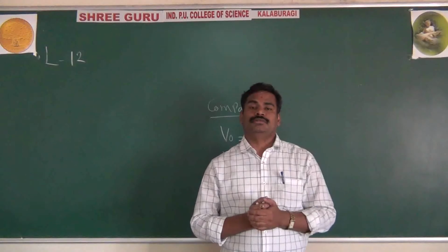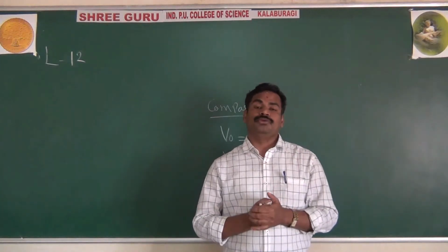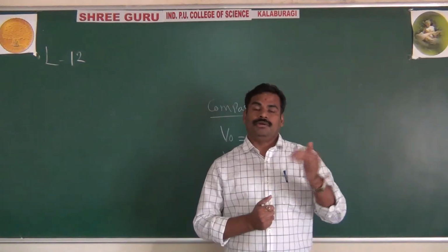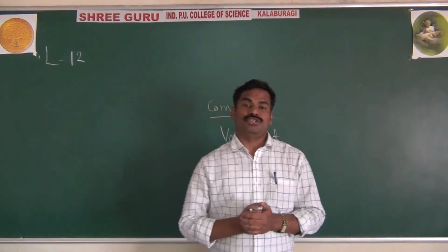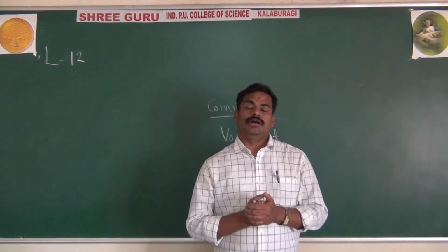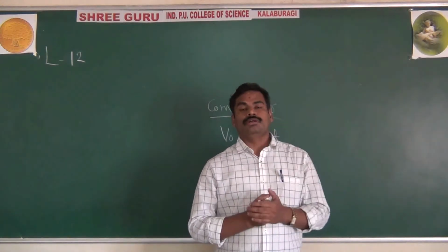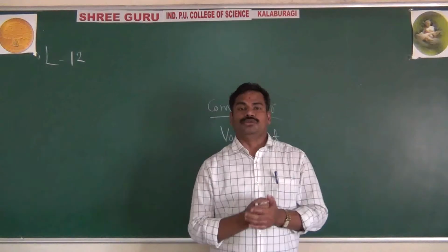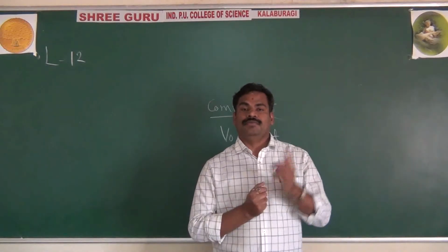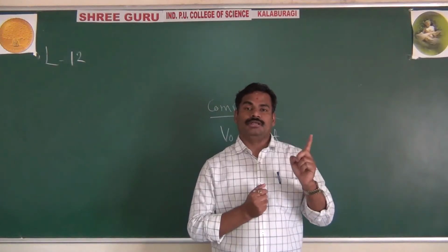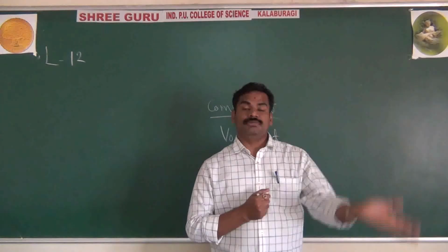The zero crossing detector is a type of comparator. In it, you apply the input to the non-inverting terminal and you apply the reference voltage to the inverting terminal. Whenever the input voltage crosses zero, the output changes. Why is it called a zero crossing detector? It is the most important application of the comparator: the comparator is used as a zero crossing detector and Schmitt trigger.